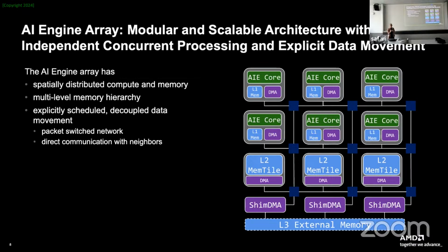And it's a little bit different than really having robots flying around. What is happening actually is that we have this interconnect network that is connecting all of the tiles in this spatial architecture. And when you want to move data around, that is where the purple boxes in this drawing will be deployed. It's always a communication with the sender and the receiver, and we use half DMAs.